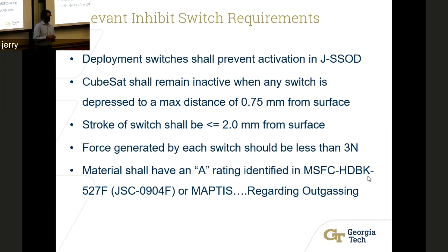And this creates a constraint on how deep our switches have to sit in our structure, which is a bit of a concern because we also have a bunch of other components in our CubeSat. And being a 1U CubeSat, there's not that much space to work with. So if our switch is very bulky and large, it'll get into the space where other components would want to be sitting within our CubeSat.